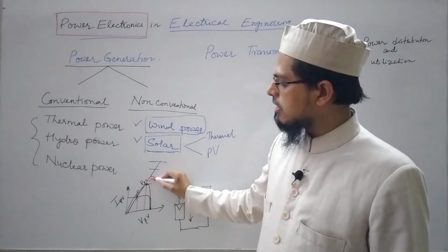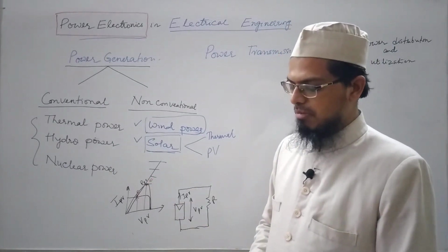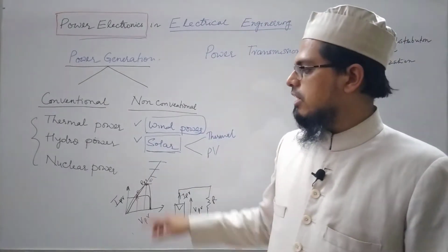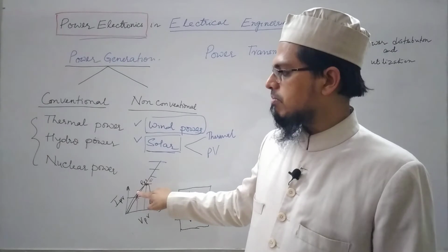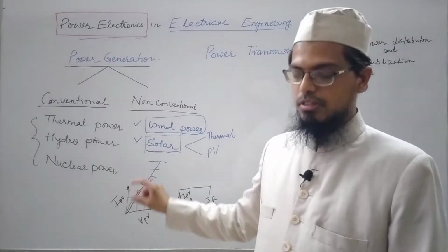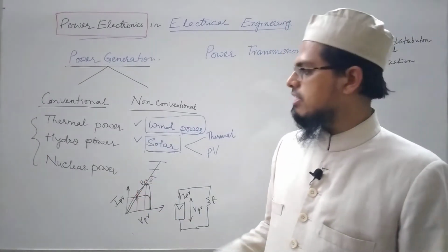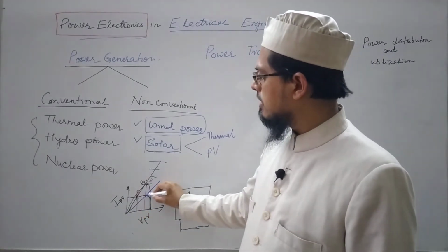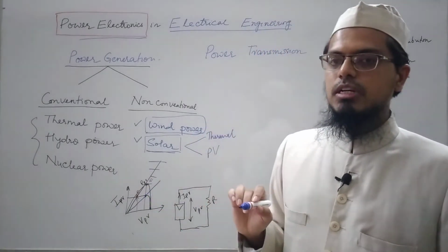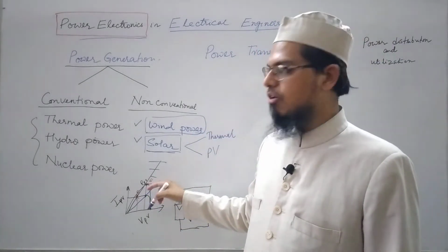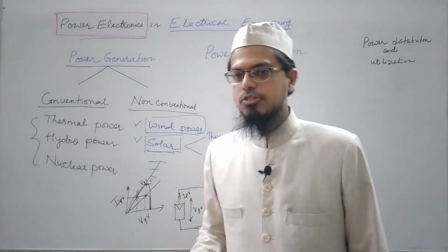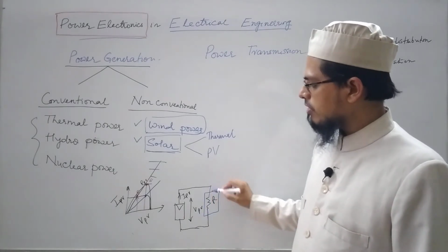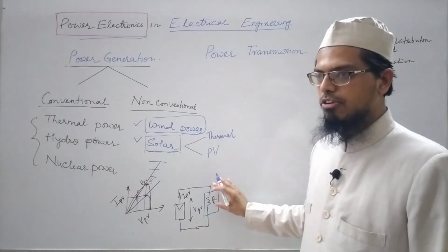So although this power can be extracted out of the panel, because of the load line it is not extracting maximum power, but lesser power. If the load line of the resistance had passed through this point, then only we would have got the maximum power. So how to ensure that this load line passes through this? This load is fixed, we cannot change it.